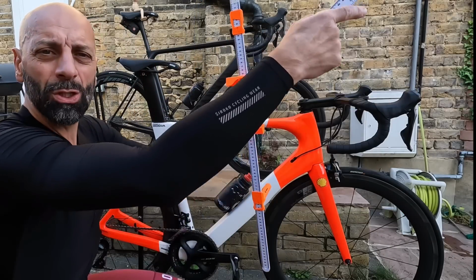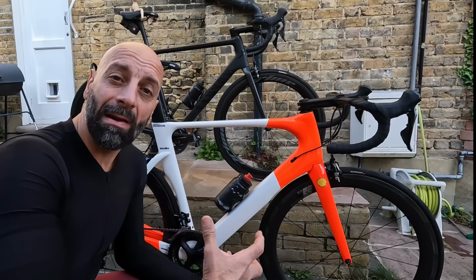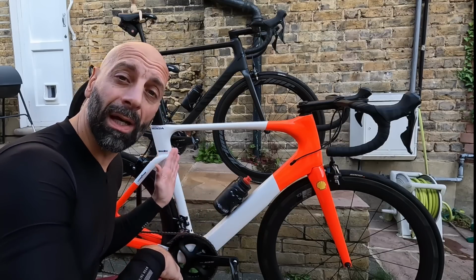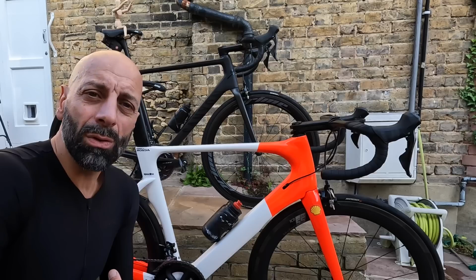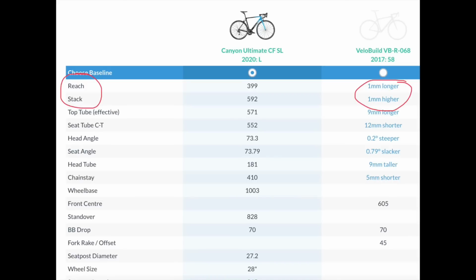However, this measurement will be giving you maybe only half of the picture, because the second very, very important measurement is the seat angle, because what happens behind the bottom bracket is as important as what happens in front of it. And this is quite relevant to the two bikes I have, because funny enough, these two bikes have the exact same front end in terms of stack and reach, so you could assume they are very similar.